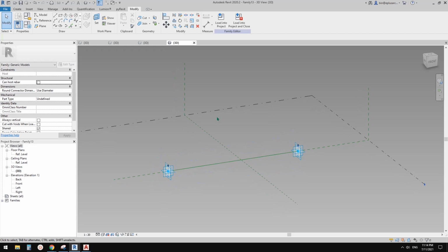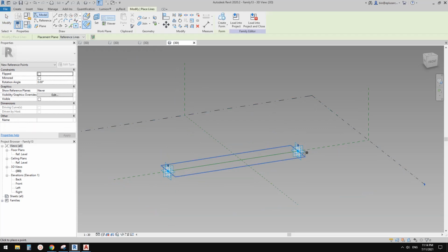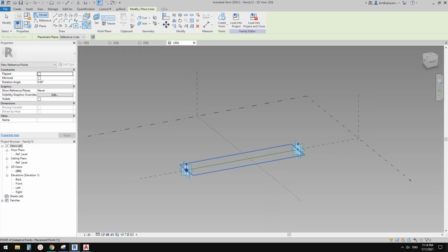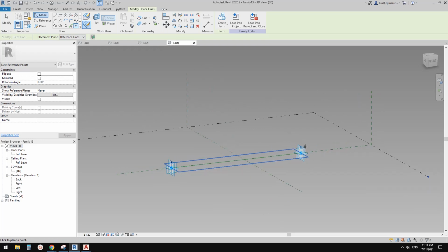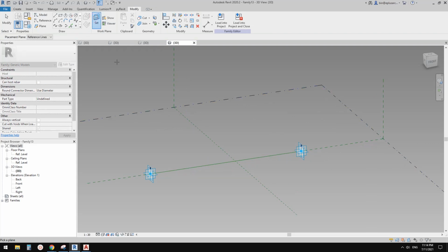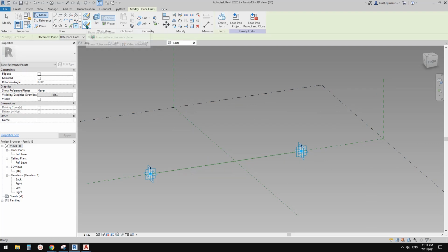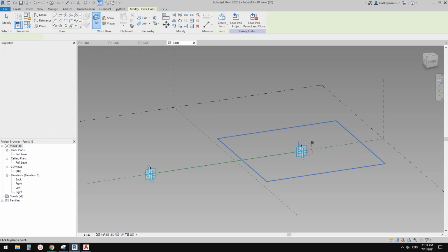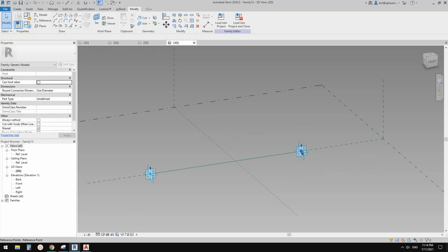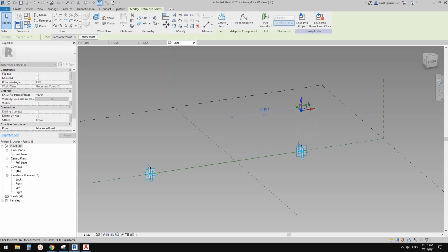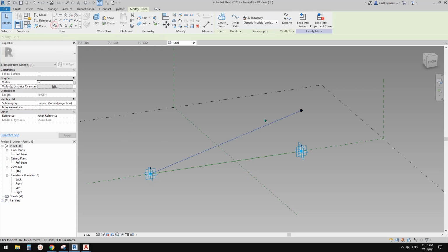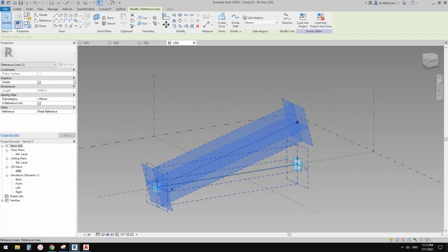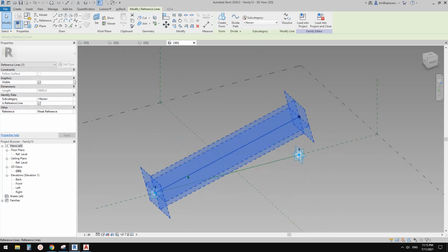So now we are going to create another point up there, so we can have an angle instead of a flat horizontal. So set work plane. Let's place a point, draw on work plane, set work plane, pick this horizontal work plane, place it on point 2, and then drag this point up. Now if I select this point together with point 1, we can create a spline, make reference line. So this will be the one we are going to place all those segments.